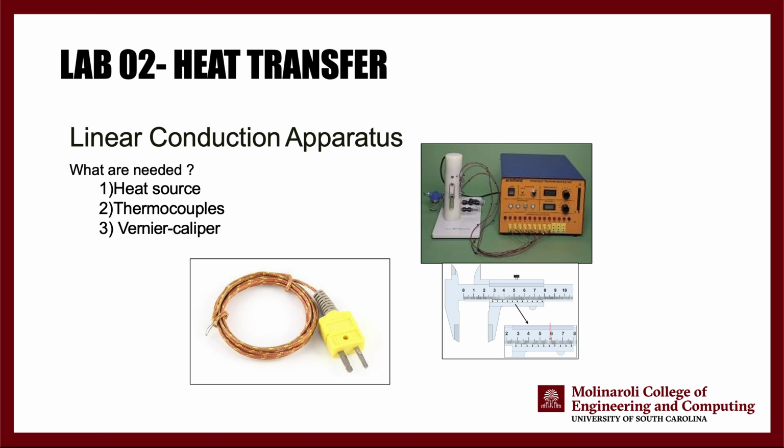Okay, so the lab itself is going to look like this. This is the linear conduction apparatus that we have in the system. You see this white part is essentially an insulation that we have to make sure that the heat transfer is one-dimensional, so we can use a simplified version of the Fourier's law.